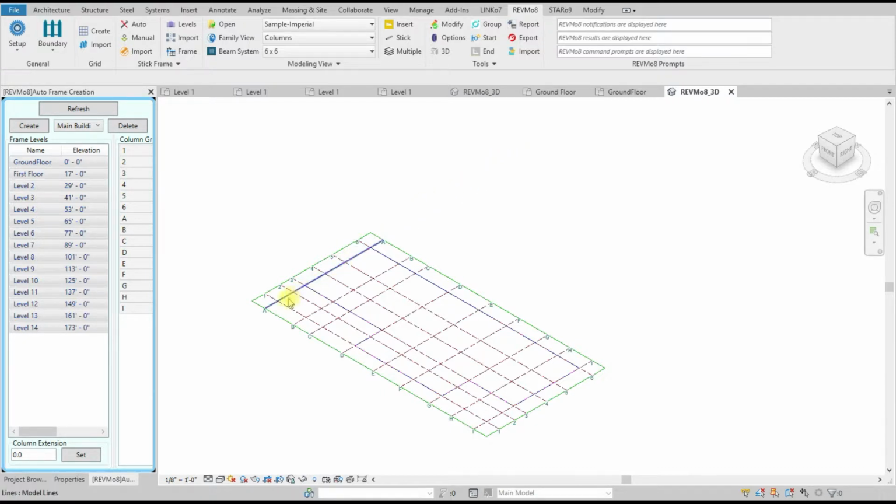So you can generate the first 4 floors and save them with a name, and you can follow that by another 2 or 3 floors, save them with a different name, and then another user would only import the first 4 floors, and so on and so forth. But before you do anything, you want to record that into a local group, so you have to click the start button here.